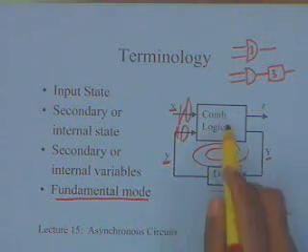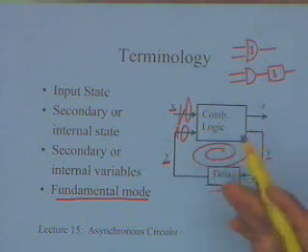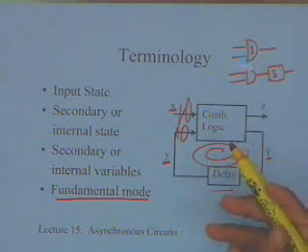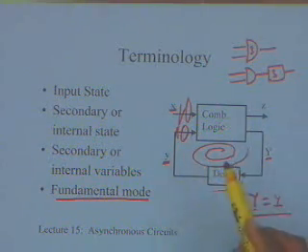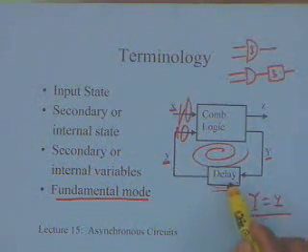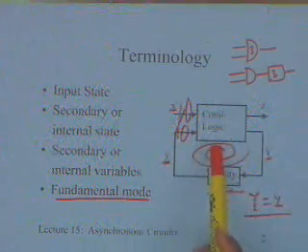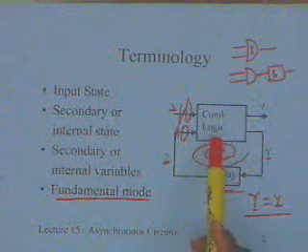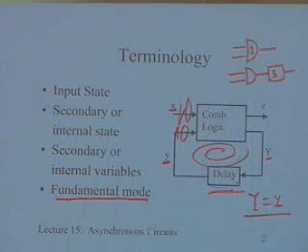This particular combinational logic has a certain delay associated with it, because any circuit that you build is going to have a delay. Typically, that delay is sufficient to ensure this, so we do not really need any component to do this. As far as the description of the circuit is concerned, we show it separately as a delay component, because on the feedback, you can assume that this is an ideal logic block which has 0 delay, and then I have the delay of this extracted out and put in the feedback path.